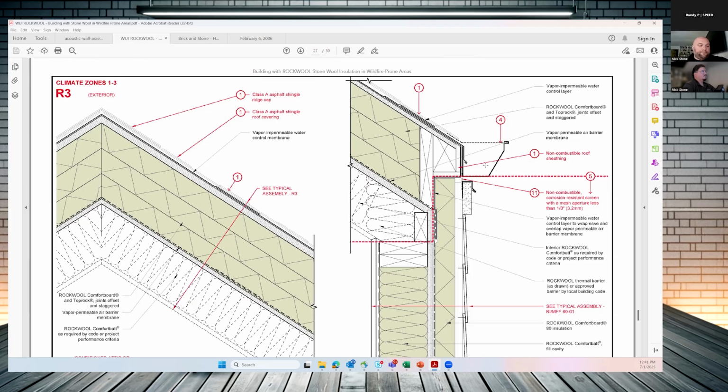And so you're now having to do continuous, and they're trying to find a way to adopt the 2024 energy code by leaving the builders the opportunity to do R13 without continuous. It's just really hard unless you find a product that can do 15. And the only two that I know of are high density fiberglass or the stone wool products. So I like to see the stuff that you have there.